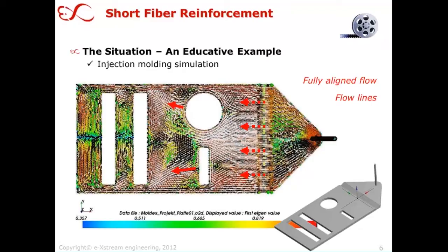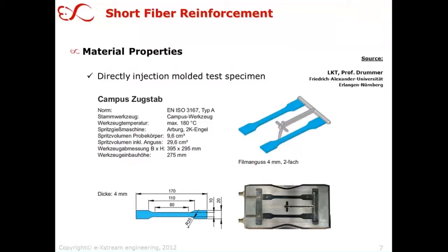And as we go along we also see the static weld lines, in contrast to the flow lines, which are basically highly aligned fiber arrangements turned in a different direction in space. The weld lines themselves are represented here by some three-dimensional stochastic distribution of fibers. So it's quite a nice example. We find very typical situations. And now we want to start, step by step, looking into the example more deeply.